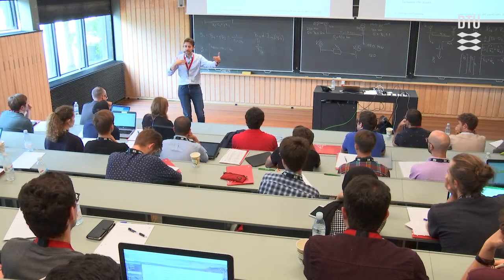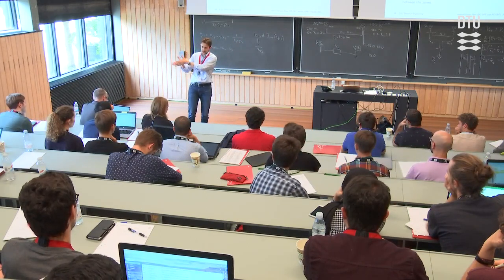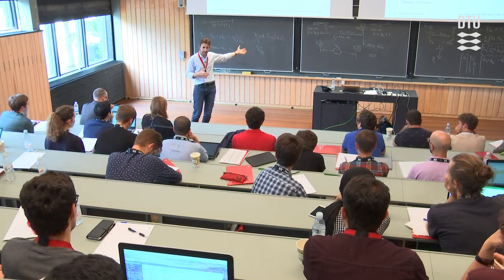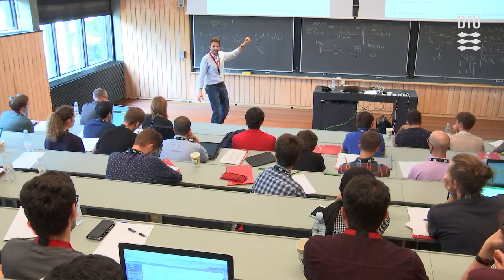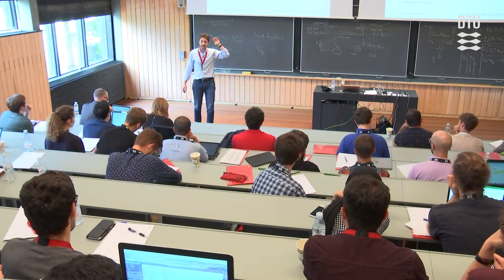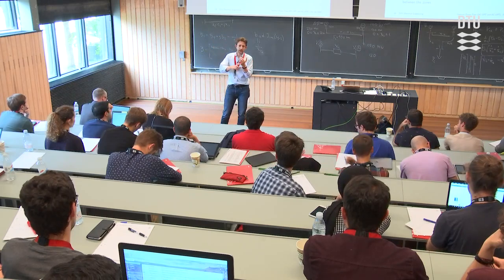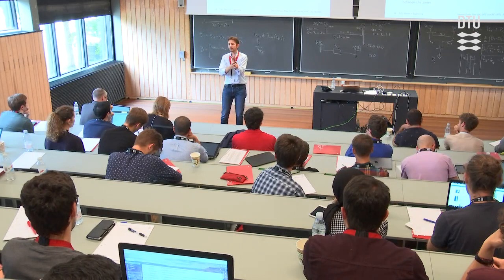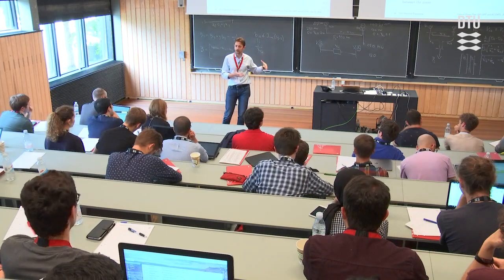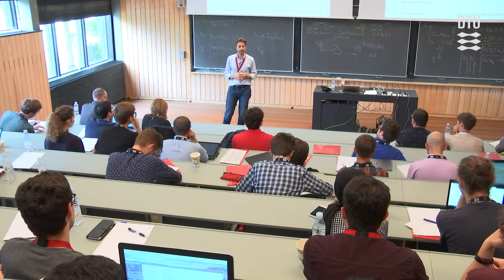An equivalent reactance between the two countries because the power is going to flow following the minimum reactance. The minimum resistance path for DC-OPF, this is the reactance. So instead of having the reactance, they have these PTDF factors. Okay, and these factors are fictitious, but they are based on the physical flows. These factors take into account, besides the physical flows, also the N-1 security criterion and other issues. But it's a fictitious number that they use for their markets, and something that has been coordinated all over the European operators.